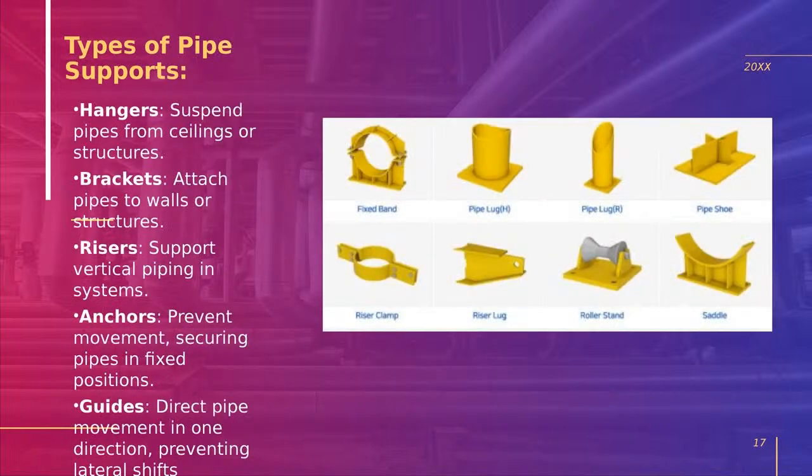Next one. These are all the major pipe supports. First we can see a clamp support, lug support, and shoe support. Mostly where we are using insulation or hard service or high temperature service, we will go for a pipe shoe. The last one you are seeing is a saddle support. That is a support we will mostly use for static equipment, like heat exchangers or horizontal vessels.